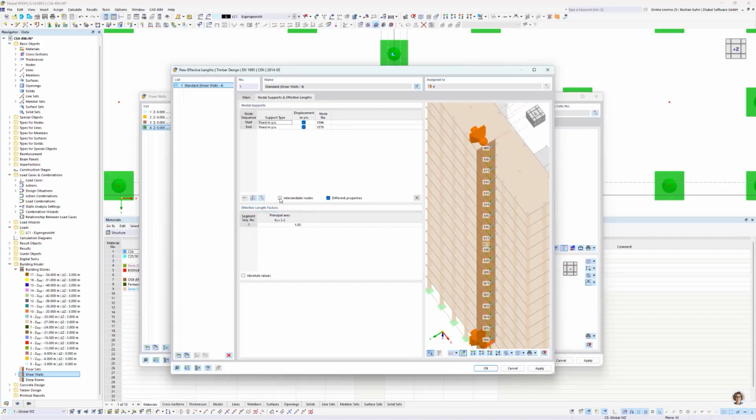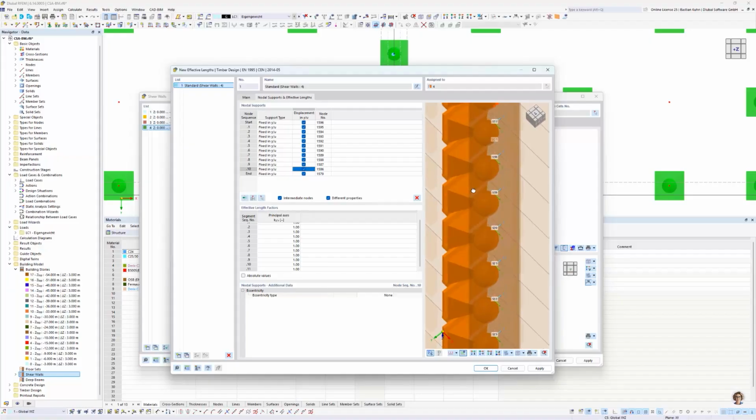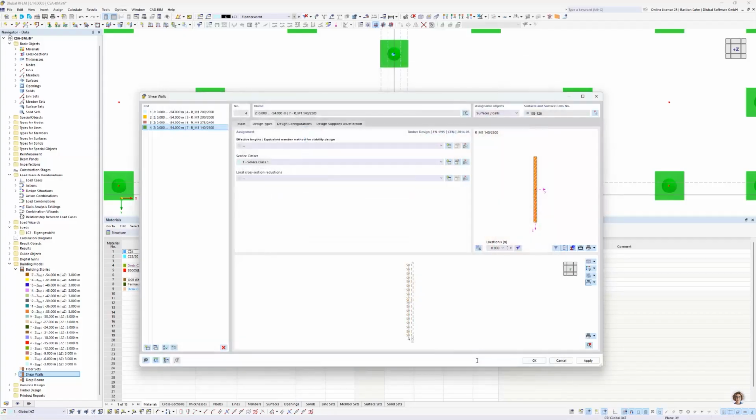And of course, we can maybe add the intermediate nodes and just activate them all. That's also possible, but we can also just simplify it. Use the minimalizing of the length. So this is possible. So let me just show that here. And now it's supported, and I'm calculating with the effective buckling factor beta equals 1 inside it, and do a simplified verification of this.